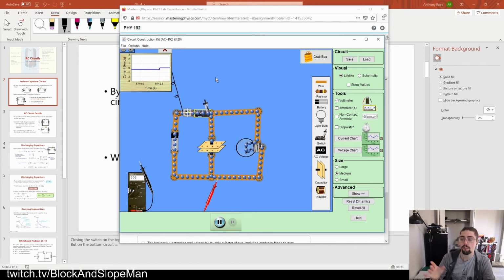And this is kind of an interesting feature, right? Because this is actually a pretty important thing. Capacitors are very, very cool because they introduce a factor of time dependence to all of our circuits, whereas resistors were just constant with time. It didn't matter whether you looked at it now or an hour from now, it'd be the same current. Capacitors depend on when you're looking at them. They depend on that time. And this kind of feature actually is one that is probably in use right now in your house where you see this fade to 0.